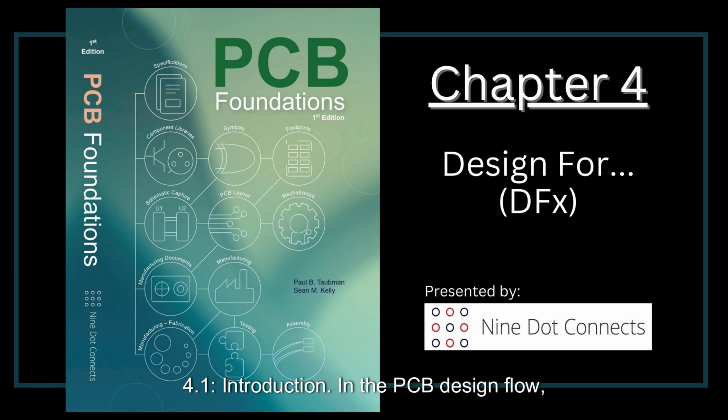In the PCB design flow, it should be understood how the manufacturing process works to get the right end product before designing for it. In fact, this philosophy of designing for something, DFX, is what we are going to investigate further. The two most important design for philosophies are DFT, design for test, and DFM, design for manufacturing.